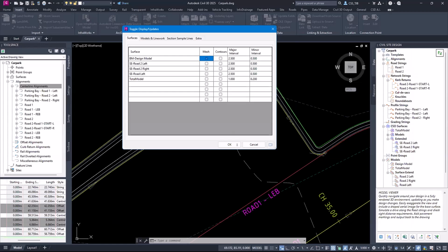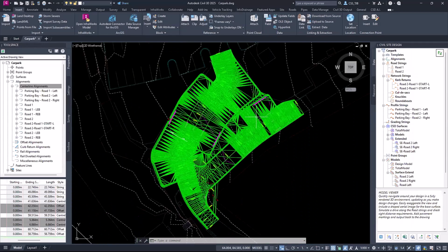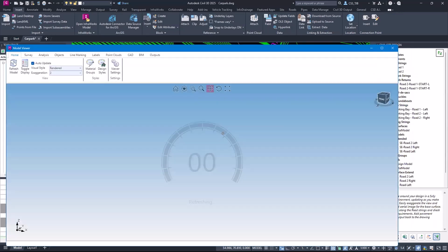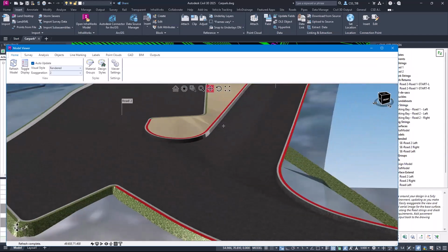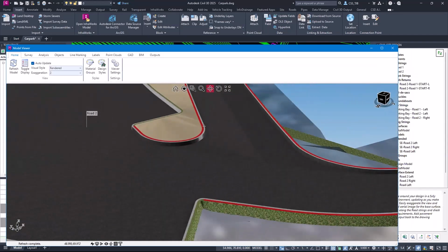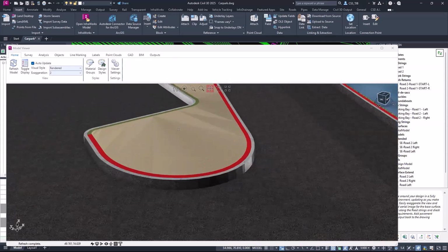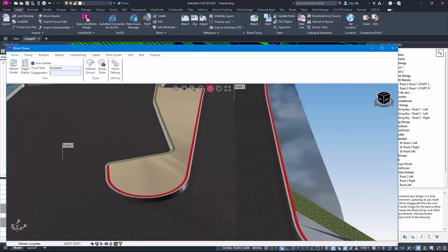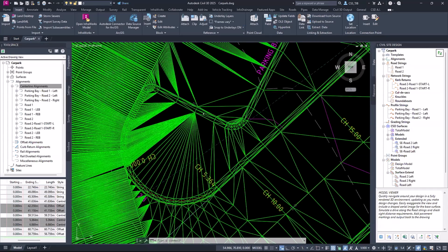I'm going to turn the mesh on and the contours again so you can see it. So you can see here now that it's just removed the batter and it just triangulates across. If I look in my model builder model in the model viewer, you can see here now it's triangulated across. Okay, so that's essentially how you can just hack things out without actually modifying the cross section. I haven't changed the cross section for those models, but I have modified it.